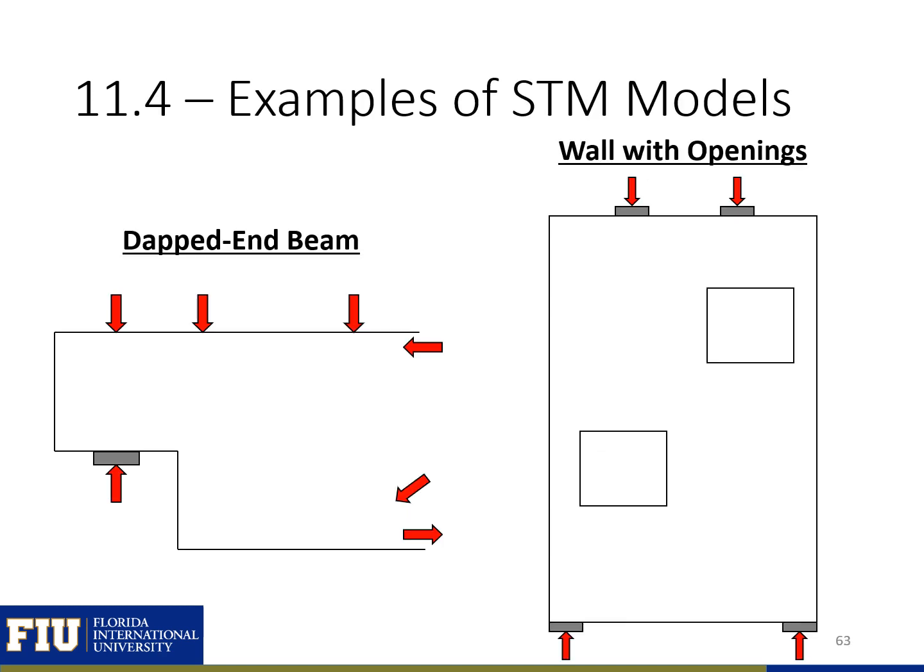On the next couple slides, I have some examples for strut-and-tie models. So if you want a challenge, then pause the video before I click on to the next slide so that you can try to develop your own model. So here we're going to look at a dapped end beam and a wall with openings. And you can see we have different loadings in each.